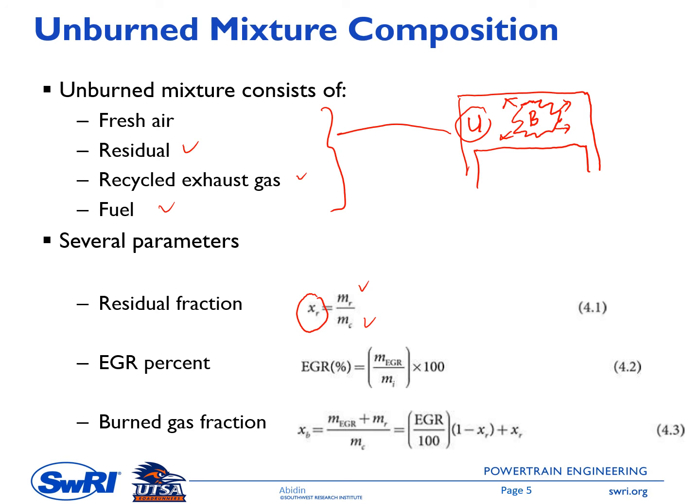So this is the ratio of the EGR mass over the induction mass. So this is the mass flow from the intake system into the cylinder. Okay, so this one is mainly air, and then might be fuel and EGR itself. But MI here is the induction mass going into the cylinder from the intake port, which consists of air and EGR. So it means we don't include fuel here.